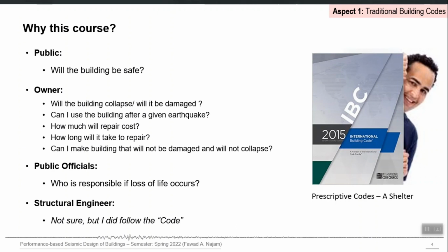So you are directly relating building performance with the hazard level, right? So you are cutting all those limits and rules and building code things from in between. Obviously they will still remain relevant, because at least you first need a starting design, and that you can get from the conventional code-based design, right? But then on top of that, you can go for nonlinear analysis to explicitly check how that design will work if this much level of an earthquake comes tomorrow, right?